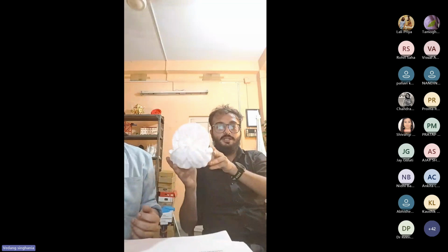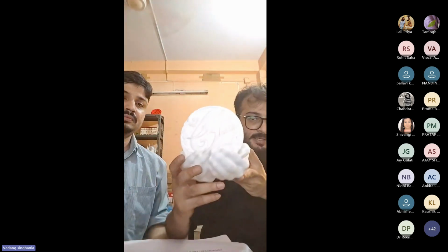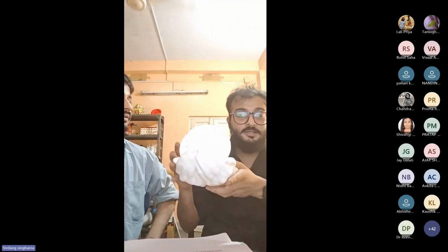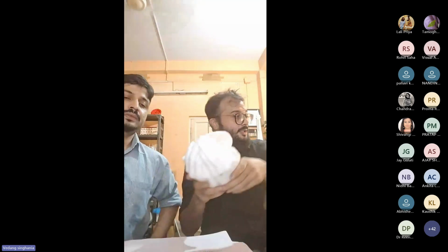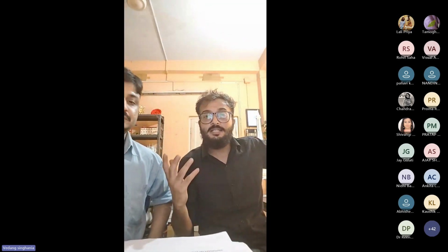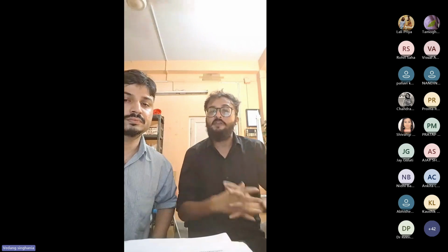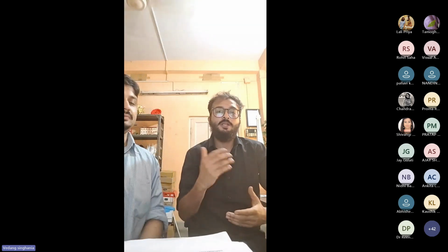For example, we did this piece. This was done in two parts. This part was printed separately and the hands were printed separately. And then we had to join it. Joining is a very crucial part of 3D printing because a lot of times we need to make really large sculptures, but our machines are not large enough. Now, you might say we can have large machines. But when you have large machines, you have a larger and wider area of failure. So we try to break up the model into a number of pieces. Then in post-processing, we either glue it, or weld it, or use a male-female joint to make the entire model stand.